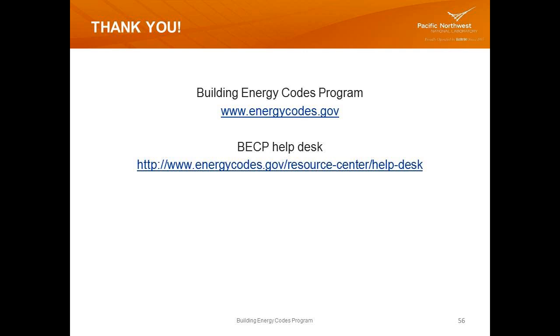IECC 2012 is companioned up with 90.1 2010. 2015 IECC refers you to 90.1 2013. If you're using the 90.1 codes, yes, they have a limit for window wall ratio and indeed skylight to roof ratios, but the methodology allows you to model the baseline or code building at the 30 or 40% level, while your proposed building will be modeled as you've designed it.